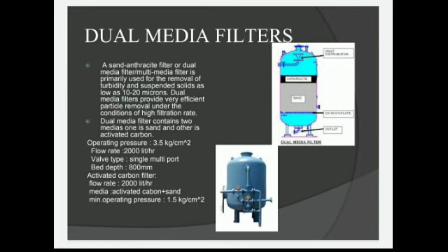Operating pressure, 3.5 kilograms per square centimeter. Flow rate, 2000 liters per hour. Valve type, single multiport. Bed depth, 800 mm. Activated carbon filter, media: activated carbon plus sand. Flow rate, 2000 liters per hour min. Operating pressure, 1.5 kilograms per square centimeter.